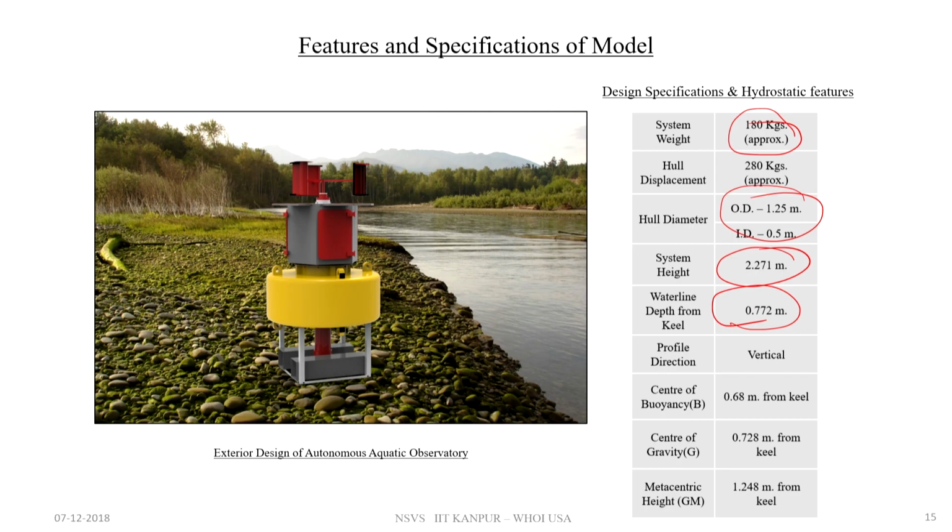And the center of buoyancy and center of gravity needed to be obtained for the system, and then the metacentric height, which gives us the GM, which tells us whether the system, even if you topple it a little bit, is going to be stable or not.